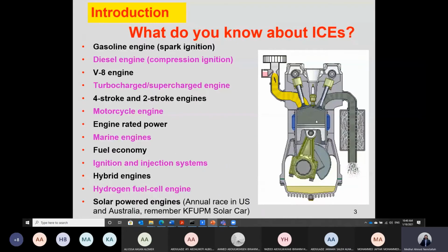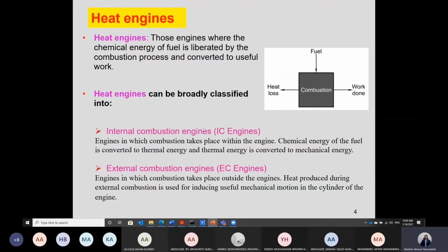So if you look here, we burn inside the internal combustion engine, and then we can generate power. The piston will be moving down. Then the reciprocating motion of the piston through a connecting rod will be converted to a rotary shaft motion. So in this case, we have burned within the engine, and we got the shaft power within the same unit. So that's why we call it in this case an internal combustion engine. We burn the fuel within the same unit in which we can generate shaft power.